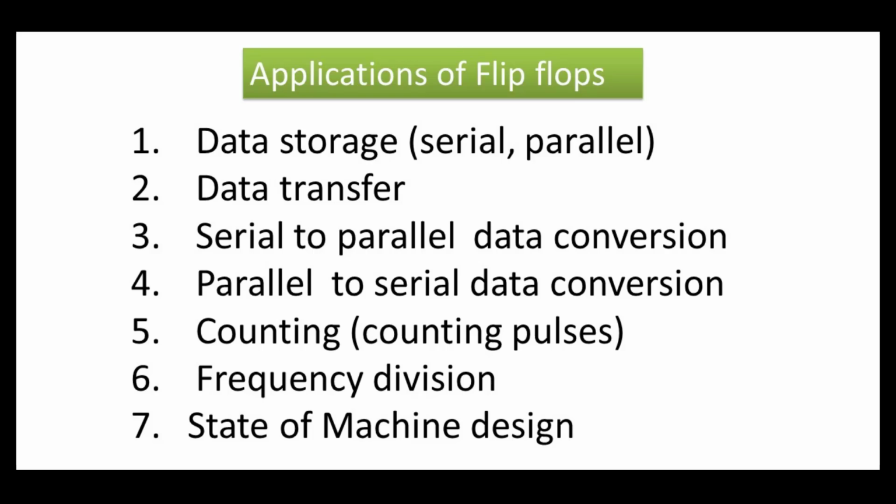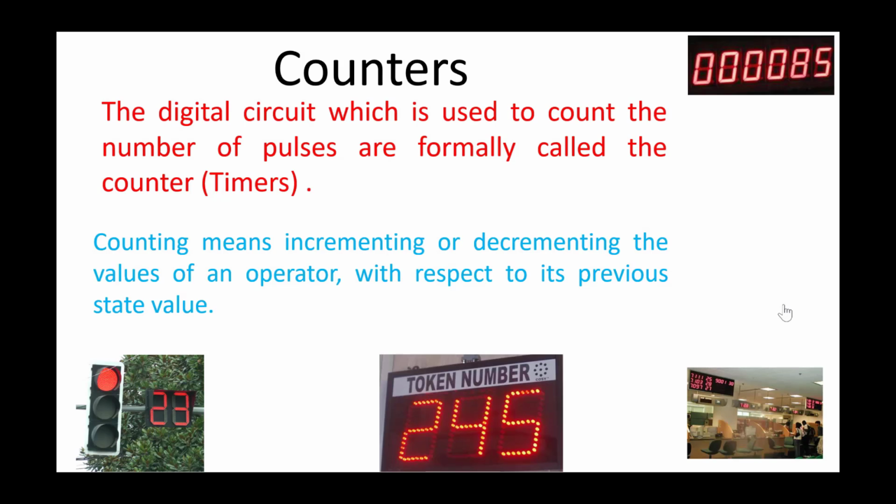In the same way, a sequential logic circuit also starts with one statement, then we give the possible input and output combinations, then we select the required flip-flop to design that particular excitation or truth table. Then we make all the connections based on the expressions achieved through the K-map. It is the same as combinational logic. The only thing is that here we have to consider a clock as well as the memory elements. The rest will be the same. So now we'll start with counters, or counting pulses, up counting or down counting.